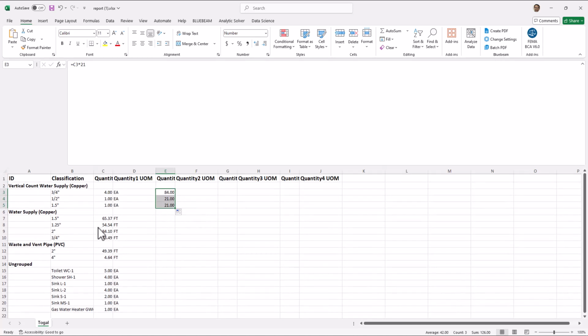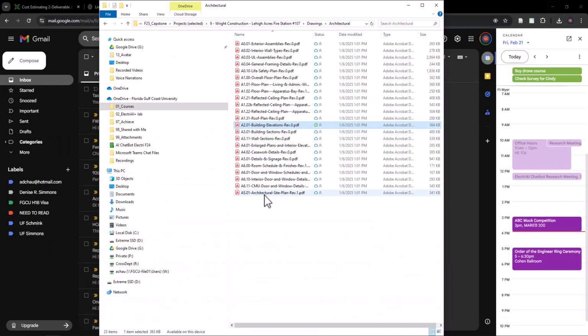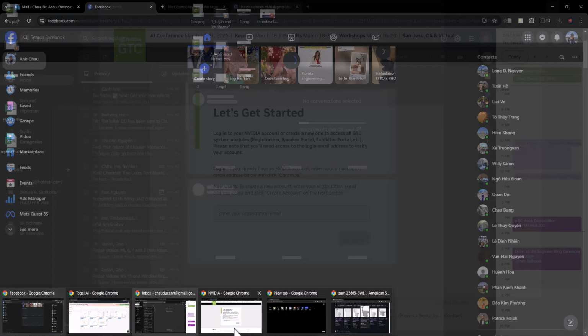So now for example the pipe 3/4 inch. So I'm gonna have this one equal to this plus 3/4 inch over here. So I have the total length of that one is 122.5 for 3/4 inch.